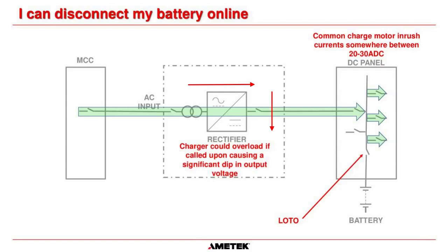And there's a lot of manufacturers that go out and sell a charger called a battery eliminator. Okay? There is no such thing as a battery eliminator. There's nothing that can replace a battery. When companies say battery eliminator, all they're saying is that this charger has a large amount of capacitors in it, and it can maintain the load circuits if it's rated for the full load of this DC panel. That's what they're saying. But in truth, do not run your DC system without a battery if at all possible.